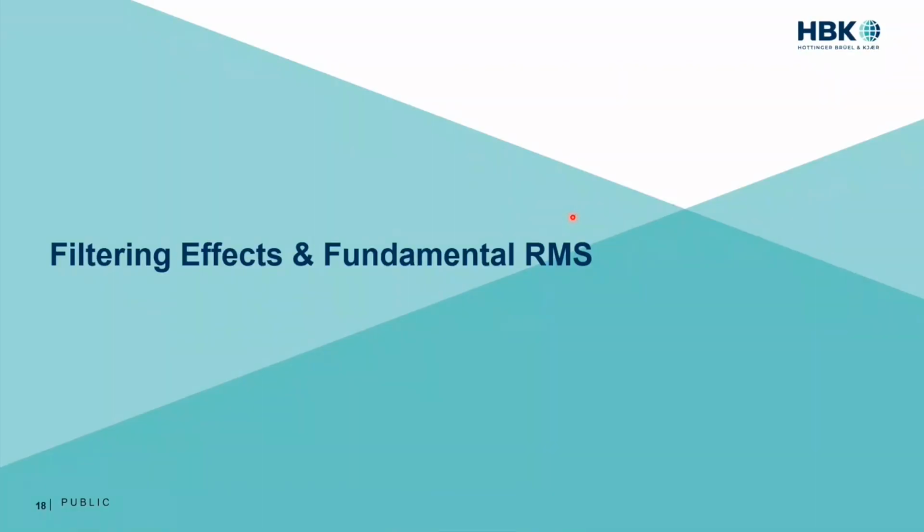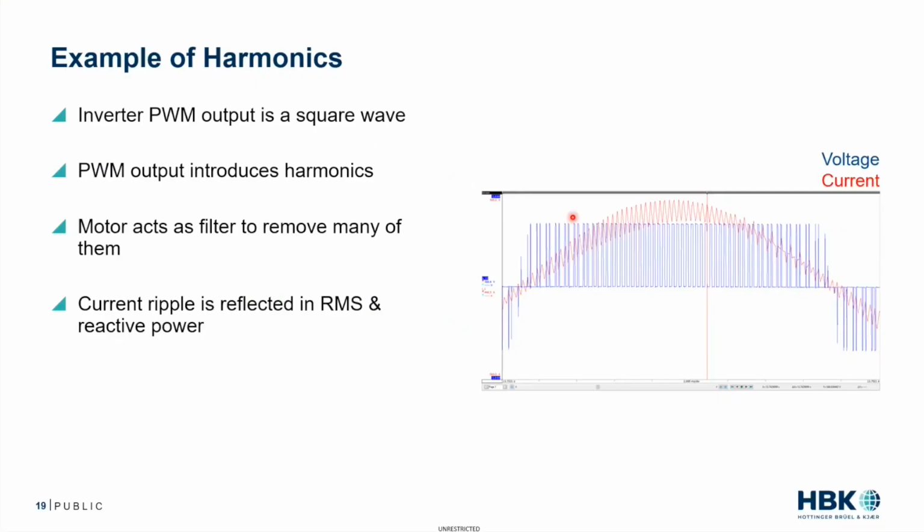Okay, now we get into the inverter driven, which is the question, or rather the inverter creates all the questions that drive me a little crazy. So here is a standard inverter waveform, again in our software, where we have a PWM voltage line-to-line measurement, a relatively low switching frequency, and we can see that current ripple.